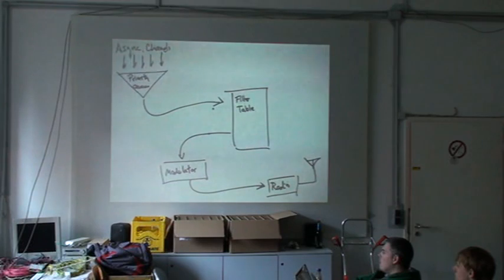So the way the filler table is structured, for any given physical channel in the GSM system, any given time slot, there's some modulus associated with that time slot. There's some multi-frame size that's associated with that time slot. And the length of the filler table for any given time slot is matched to that multi-frame size. So there are actually commands in the control interface for OpenBTS with the transceiver where you tell the transceiver what multi-frame size you're transmitting on a given slot. The reason you're telling it that is so that it can configure the filler table.